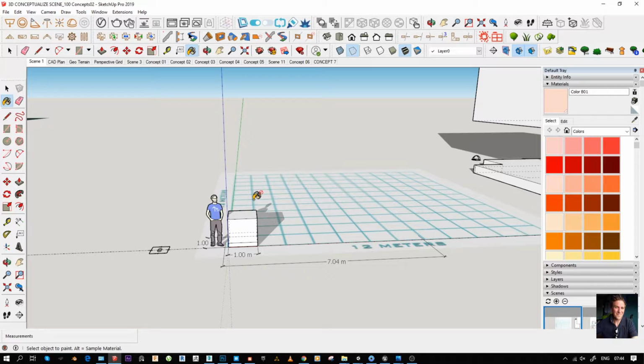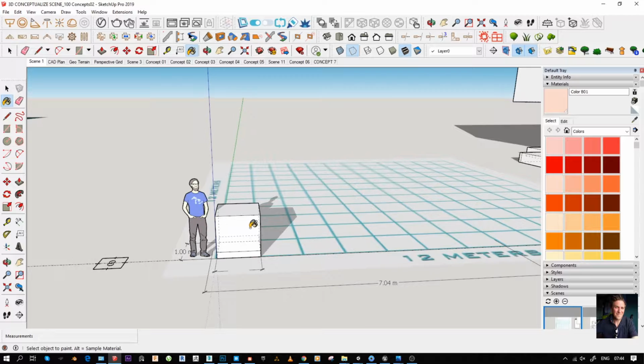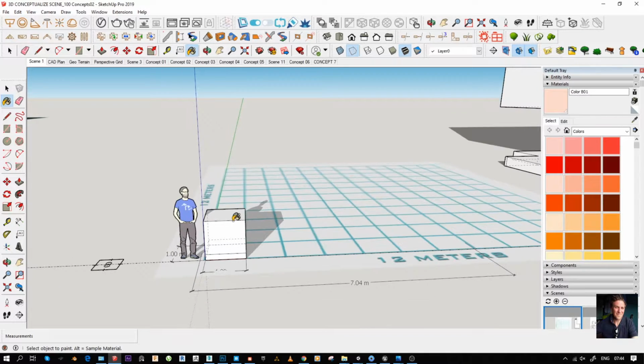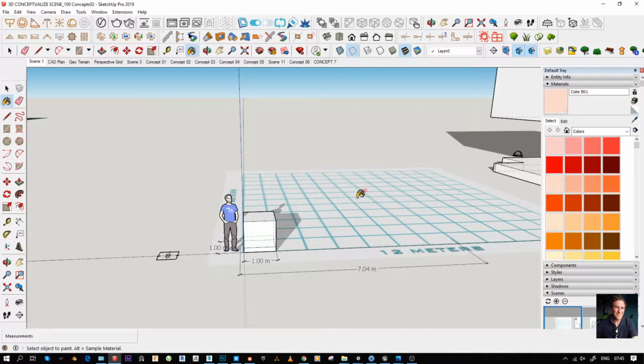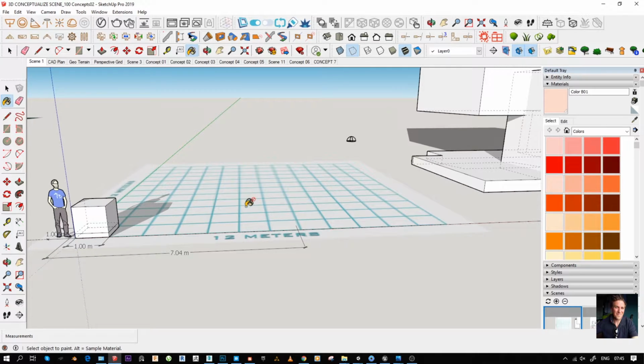And for matching up your image in your scene with a 1 meter cube, I have a different tutorial online for that, showing how to use a tape measure tool and how to rescale elements. So basically, setting up scenes is very useful in SketchUp, because unlike 3ds Max or Maya, you don't have those separate viewports of different elevations and perspective, different orthographic viewports. So I set up scenes.